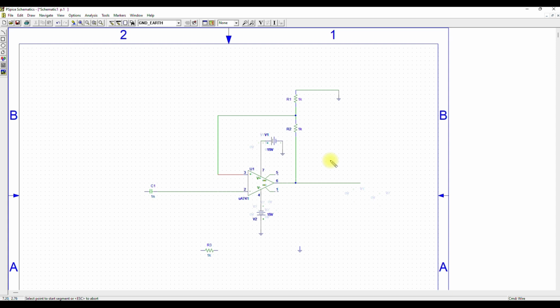Okay, and now I need to connect the resistor, that is R3. So take a connection from R3 and connect it over here between the capacitor and the inverting terminal, that is the negative terminal. Okay, and also I need to connect the ground to the capacitor. So again take a wire connection, the other end of the capacitor is connected to this ground. That's fine. Then this resistor is connected to the output of the op-amp. So the connection is successfully completed. Now I need to give the values for each and every component. So first I need to give the capacitor value.